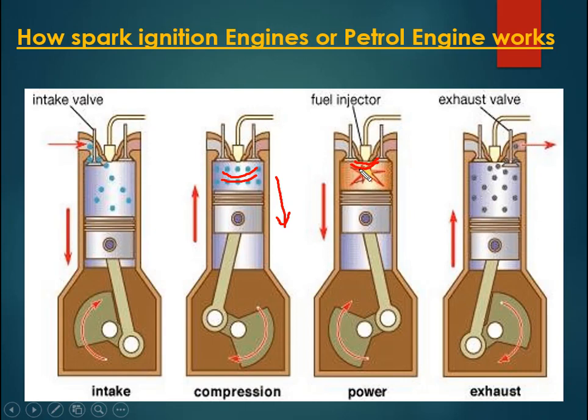But due to this combustion reaction, it may be possible that some other part of the fuel-air mixture ignites without being reached by the flame front, and because of that another pressure wave front is created. When both pressure wave fronts hit each other, a knocking sound arises. So there could be two possible mechanisms by which knocking may take place.